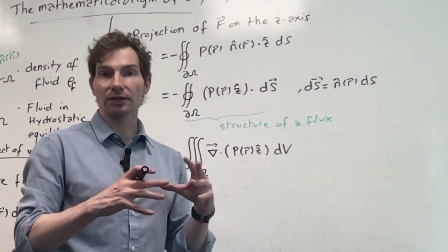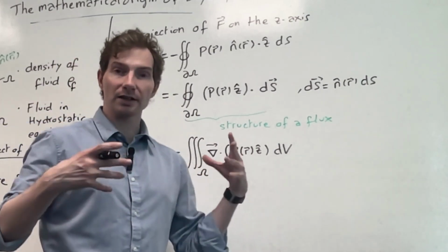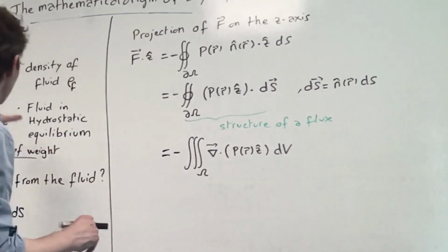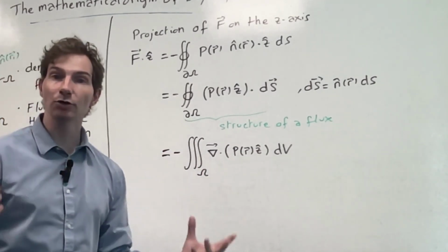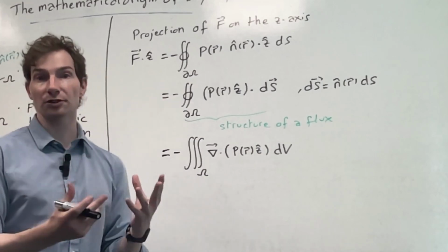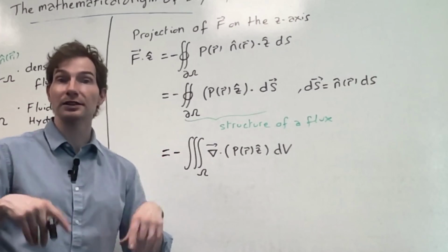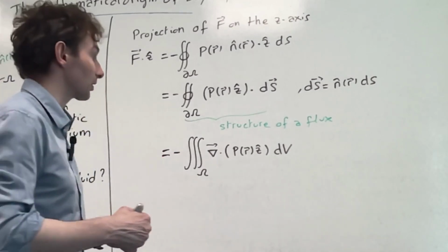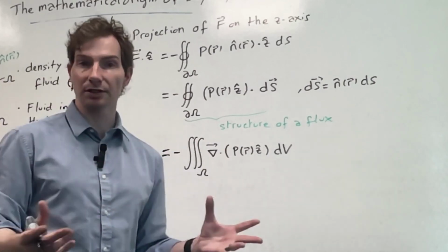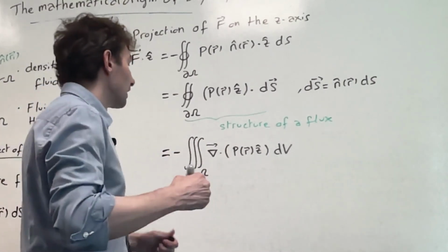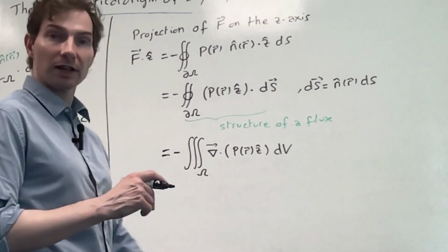And the thing is that here, again, what I need to imagine is that it's as if I had removed that particular solid object, and then I'm looking at how the fluid is going to behave and how the pressure field is going to behave within that region. So that's what we are imagining. It's as if we had removed the solid part here. Now, once we have done that, I need to find out what is the divergence of that.